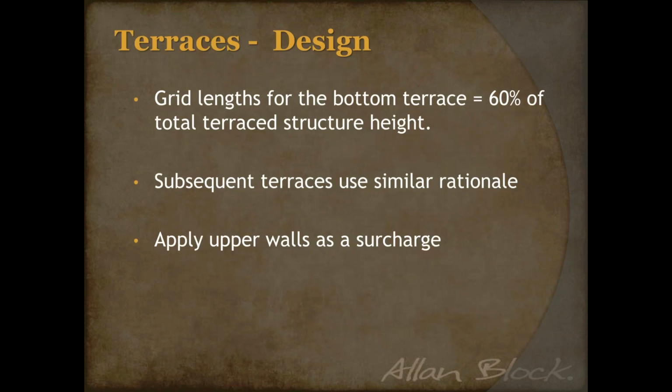So, first thing is you want to design your terraces. How do you design them properly? First thing you want to do is we have some rule of thumbs out there on how to design terraces. So I'm going to go as if you're plugging it into our AB Walls design software. I'm pretty sure that there's plenty other softwares out there. I'm not sure any of them at the moment do full terrace designs outside of global stability programs. But for the standard retaining wall design software, you're going to follow the same concepts.